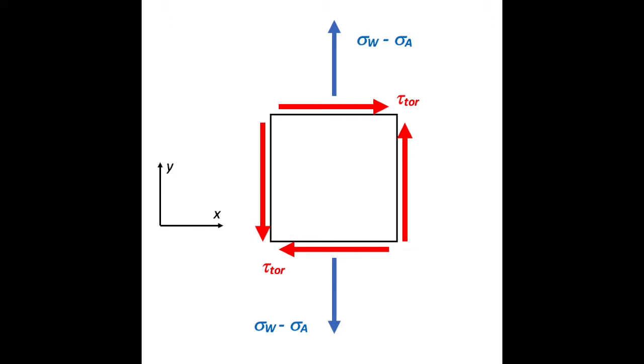to that movement. If we took this piece of 2D material, a counterclockwise twist causes the top of it to shear along the positive x direction, so we draw an arrow to the right along the top. We then draw an arrow in the opposite direction on the bottom to maintain force equilibrium.